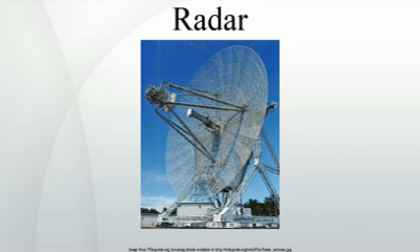Certain radio frequencies that are absorbed or scattered by water vapor, raindrops, or atmospheric gases, especially oxygen, are avoided in designing radars, except when their detection is intended. Radar relies on its own transmissions rather than light from the sun or the moon, or from electromagnetic waves emitted by the objects themselves, such as infrared wavelengths, heat. This process of directing artificial radio waves towards objects is called illumination, although radio waves are invisible to the human eye or optical cameras.